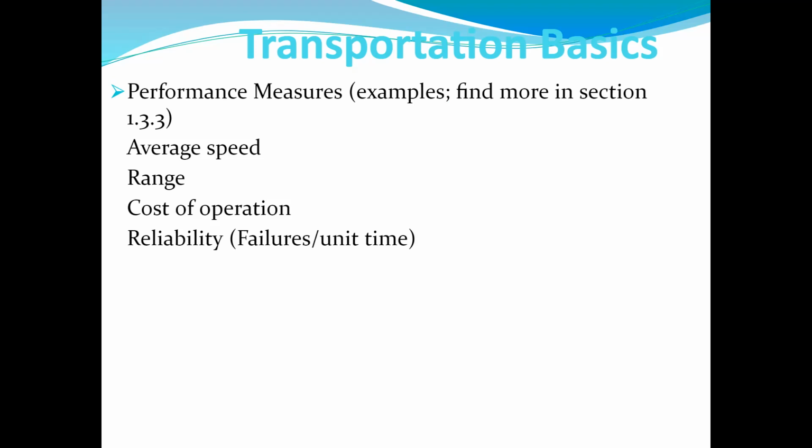We don't design it for the highest possible hour in the year. So for example, we don't design a roadway system or a signal or whatever it is for the highest amount of traffic that we'll see in an hour over a year. No, we don't design it for the worst hour. We design it for the 30th worst hour. So we expect the system to fail or people to face congestion for 29 hours of the year.